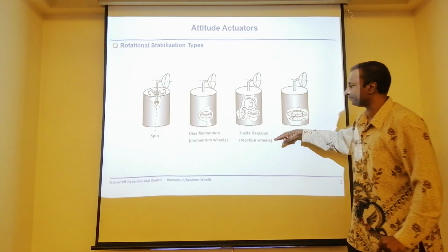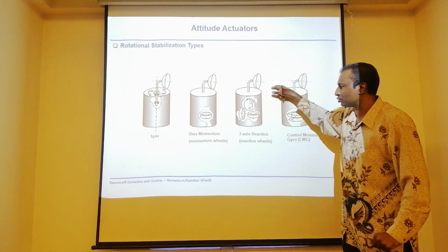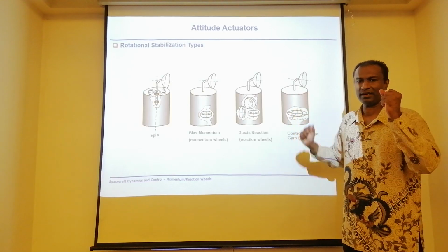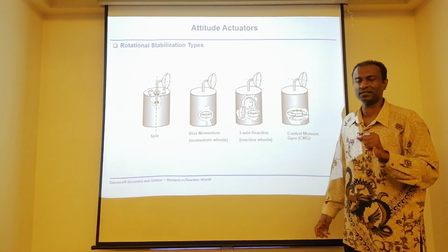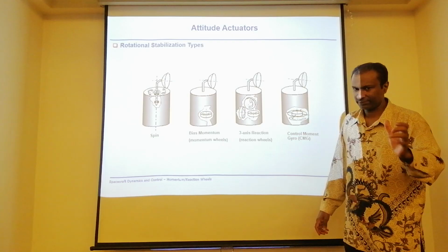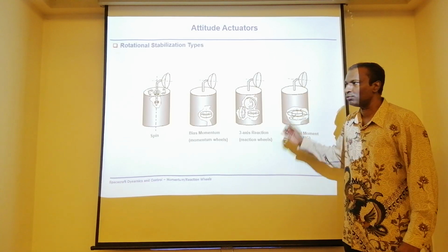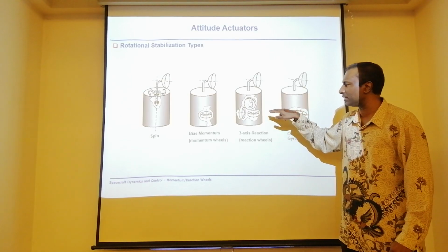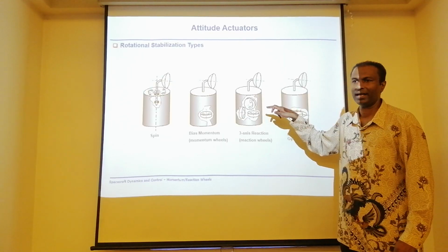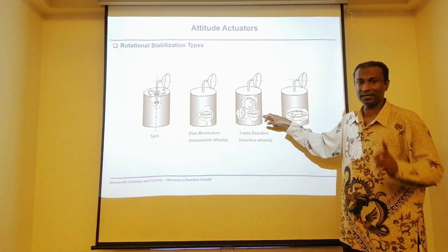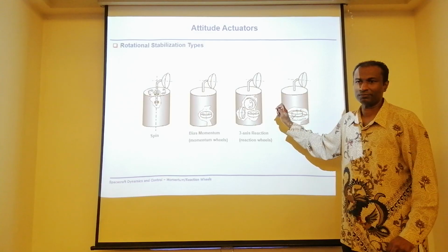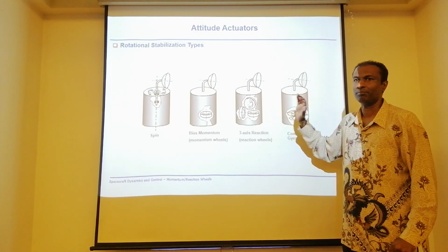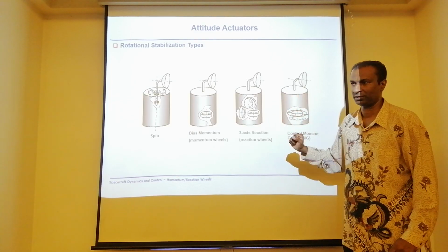Now attention, all those satellites, very precise pointing satellites, expensive as well. You will see that more often than not, they will come with 3-axis pointing. Using reaction wheels will be one of the most common options.